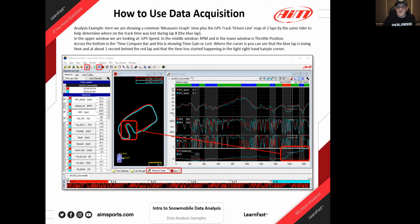And John had asked, how do you break it down into laps? If you don't have the track mapped out prior or after the first practice, it will always, if the track is mapped out, it'll always go to there since you're nearby it. But you could go to the lap manager tab and then insert the start finish line with your cursor. And we can show them that when we get into the live data. Yeah, we'll show that to you real quickly.